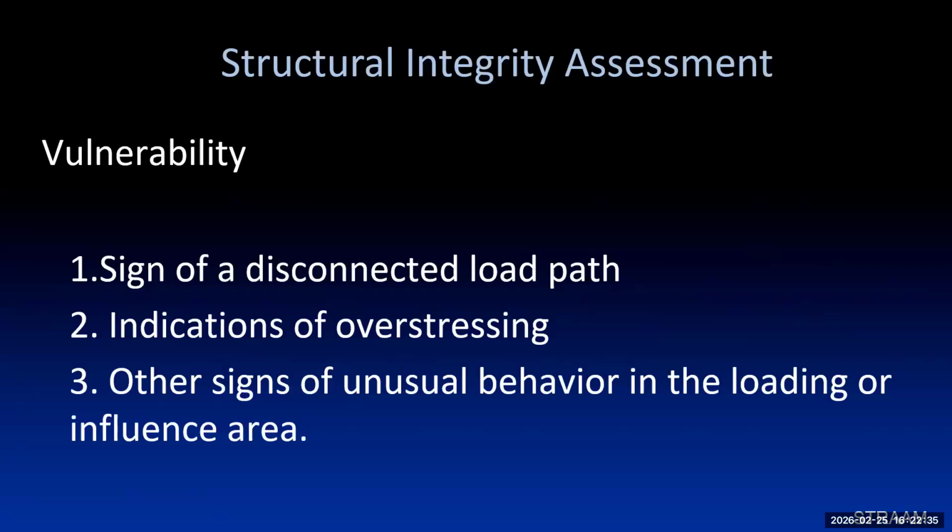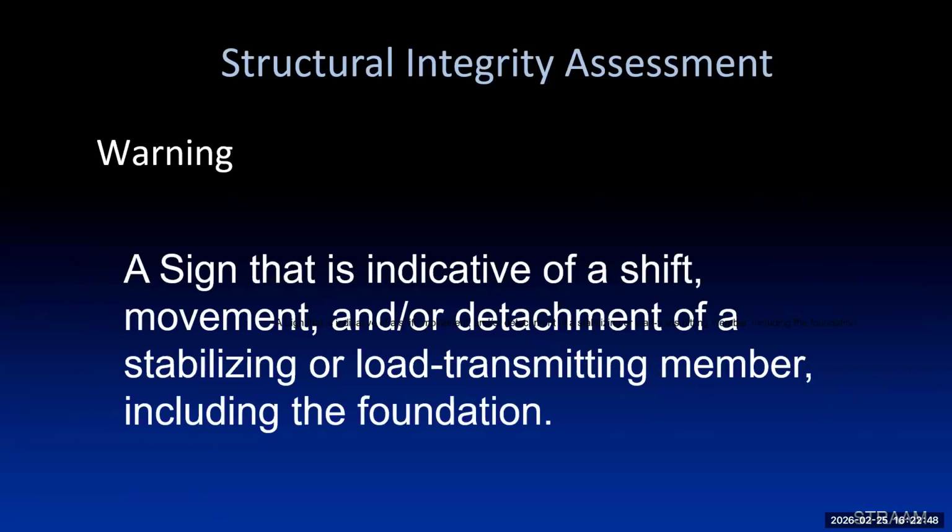It may be an indication of overstressing. Other signs may be unusual behavior in the loading or in the influence area. A warning: a sign that's indicative of a shift, movement, and or detachment of a stabilizing or load transferring member, including the foundation.